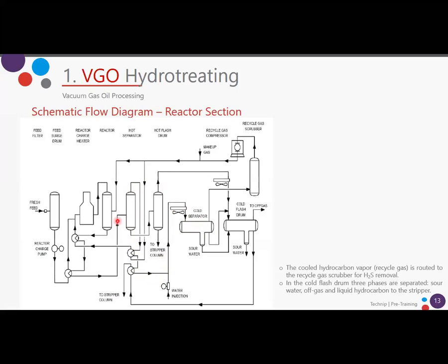In the first separation, you will recover most of the hydrogen that you will send back to the reactor. This first separation gives the lighter components that you recycle back to the reactor as a quench, and also to join the feed here. Then the other one will have more methane and ethane that will go to the off gas, to be treated for fuel gas. So yes, you are right.